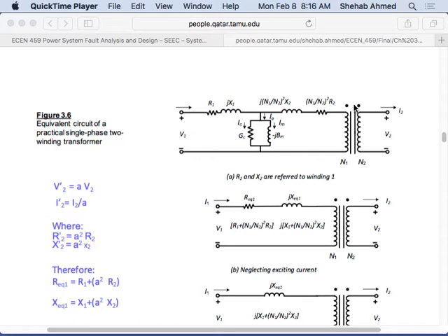Is it important? Is it considerable? We said it's not very considerable, right? So what's going to happen is if I put a voltage source here, that I raise slowly, and I put a short circuit, then I would be able to push rated current in the transformer. If I push rated current in the transformer, then I put a voltage, rated current will flow.